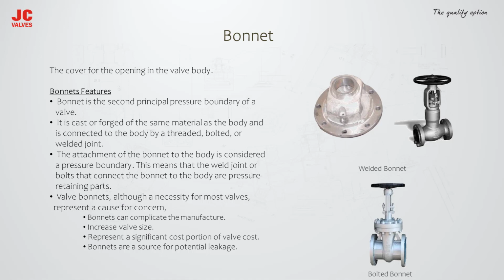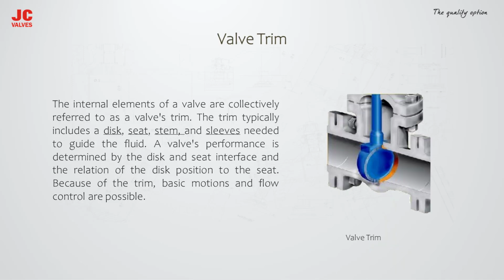Valve bonnets, although a necessity for most valves, represent a cause for concern. Bonnets can complicate the manufacture, increase valve size, and represent a significant portion of valve cost. Bonnets are a source for potential leakage.